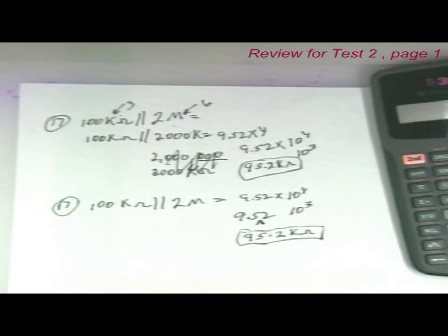Now if you have four 100-watt lamps connected in parallel across a 120-volt source, what is the total current? Well, you have to figure out what I is. If you're given P, which is the 100 watts, and you're given E or V, which is 120 volts, then it's easy to figure out current. You know the formula, you're going to have that formula on your formula sheet.